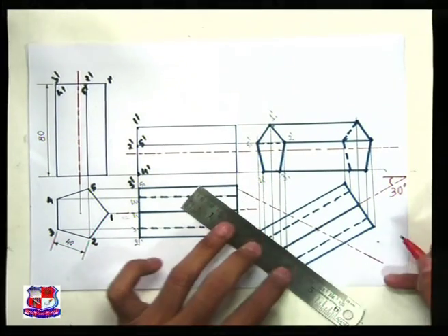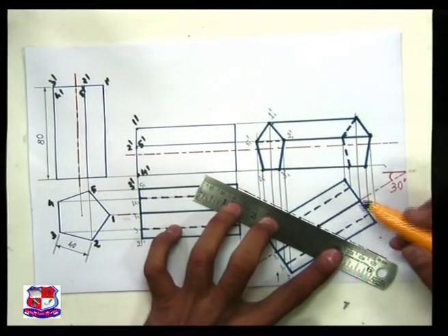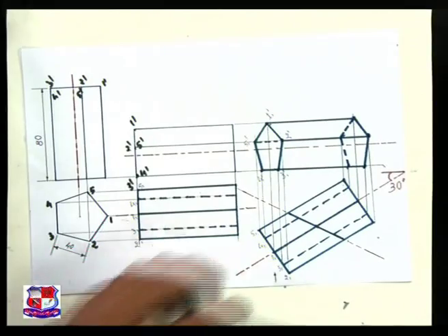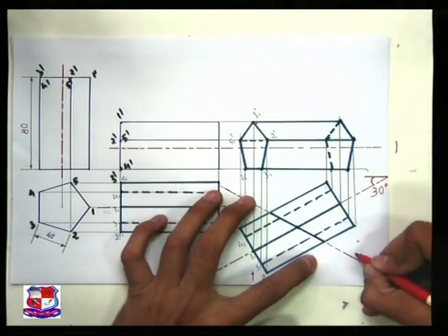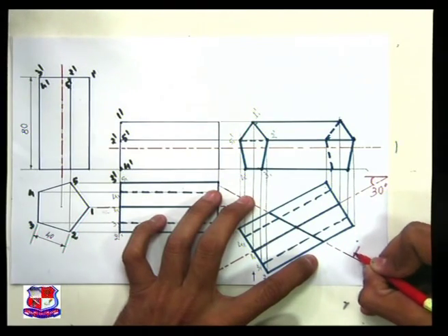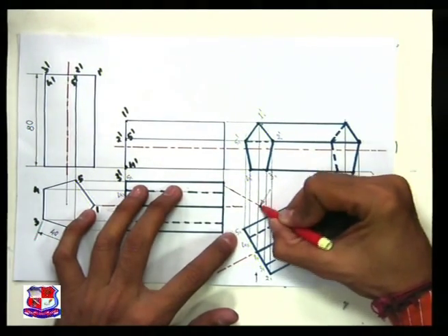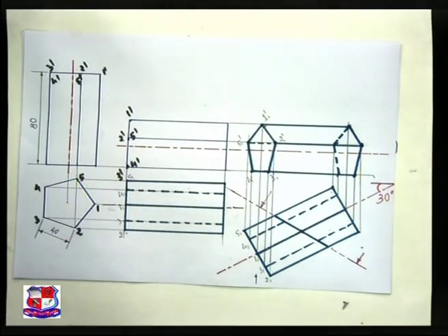This should be a darkened one, and this is the cutting plane. So you can draw this cutting plane like this. This is the cut portion, right? And here material is retained, so draw arrows like this. It means that this material will be retained and this material is removed.